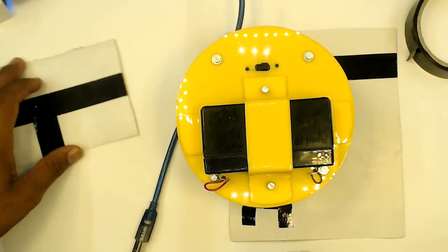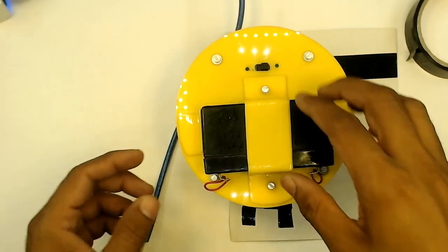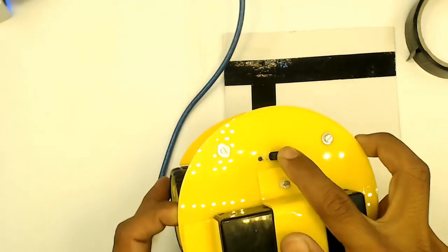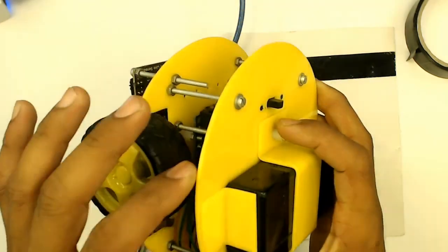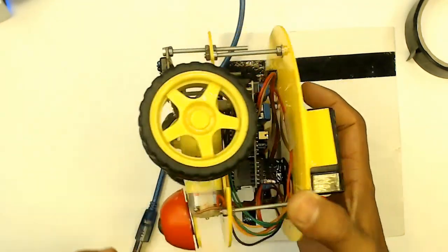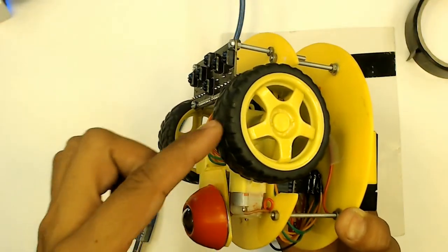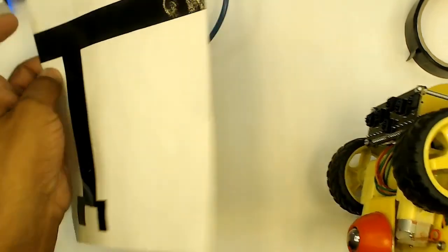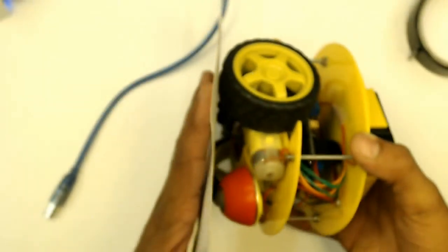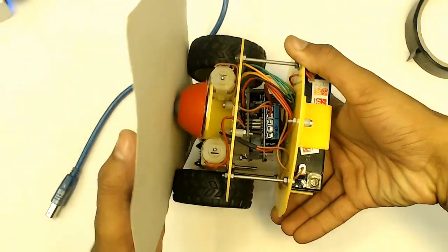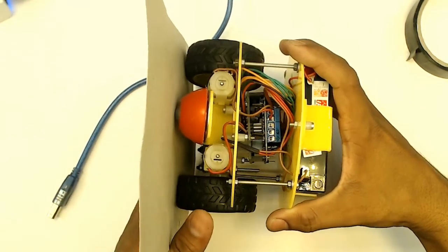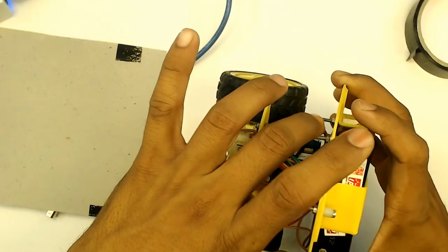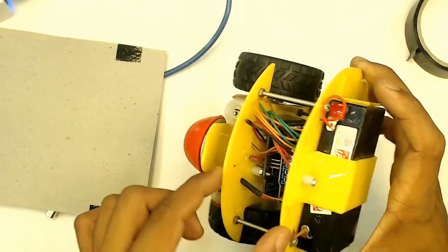So a couple of things to be kept in your mind whenever you are dealing for the first time, that is whether you have this button or not, whether you have this sort of chassis available, or what kind of motors, what kind of wheels you have. Keep in mind a couple of things. So the first thing is you need to place this chassis in a very structured manner. So I have used these screws and nut bolts to properly maintain a spacing in between.